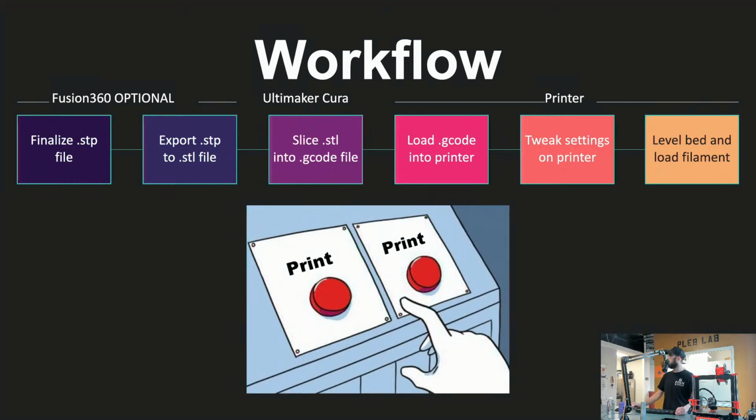Download it from the source if you would like. After you have set your parameters to go and print, again, how hot you are printing, what material, how thick, big, tall, you will export that as a G-code file. I apologize, I do not remember what the G stands for. I'm going to guess off the top of my head geometry, but I'm just going to assume, and you never should assume, but it is the geometrical format which your machine needs to move to go and build